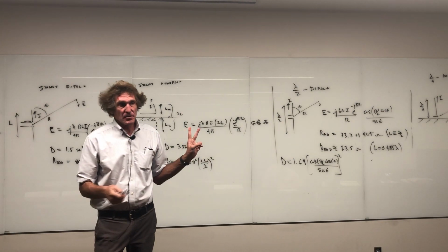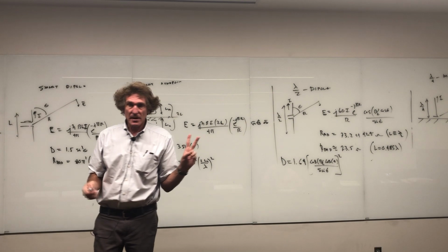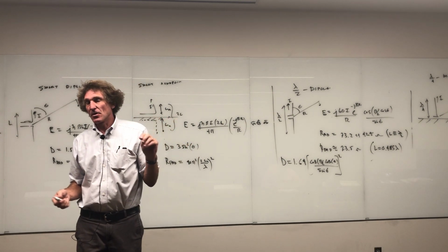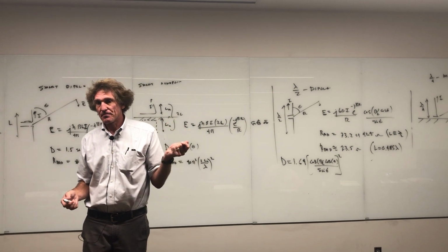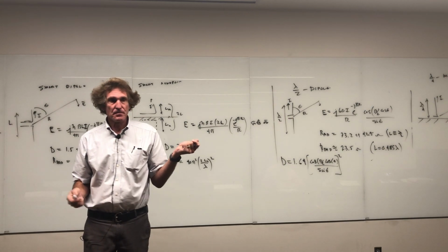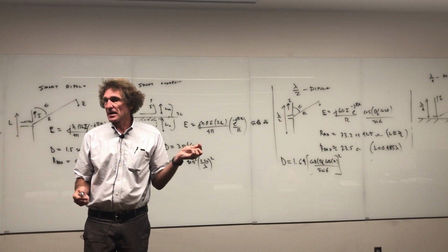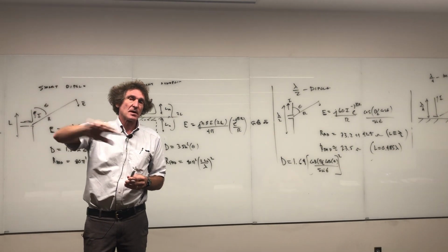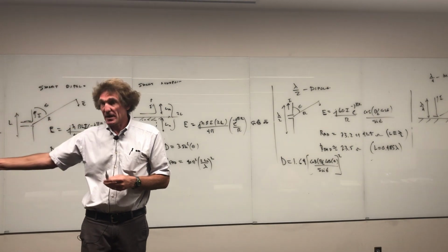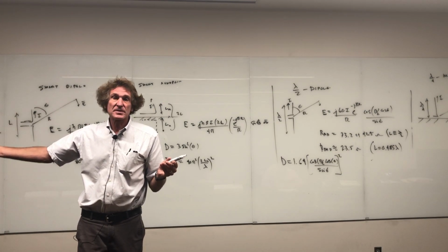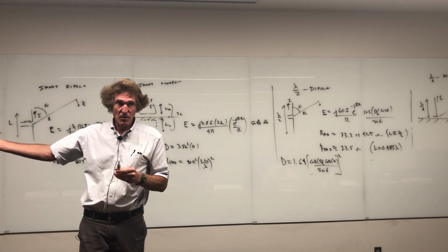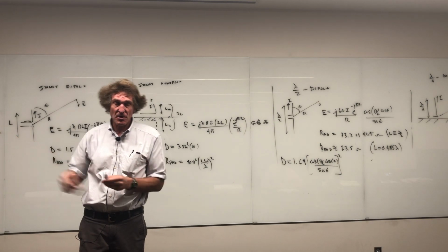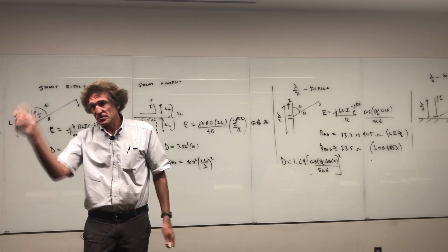The second thing they do, I don't know if it's legal in Alabama, you can buy a thing called copper sulfate. Does anybody know what that is? You know what a water resistor is? Anybody? All right, here's the thing. Some of you will be involved in this at some point. When you have anything that stores a lot of energy, like large capacitors that are part of a system, when they get charged up, if you want to go in there and do anything, you want to safely discharge them. Well, electrolytic capacitors, you can't just short out.